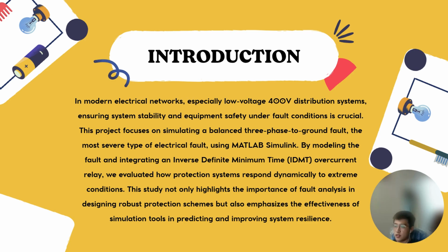This project focuses on simulating a balanced three-phase to ground fault, the most severe type of electrical fault, using a MATLAB simulator. We do the simulation by modeling the fault and integrating an inverse definite minimum time (IDMT) overcurrent relay. We evaluated how the protection system responds dynamically to extreme conditions. This study not only highlights the importance of fault analysis in designing robust protection schemes, but also emphasizes the effectiveness of simulation tools in predicting and improving system resilience.